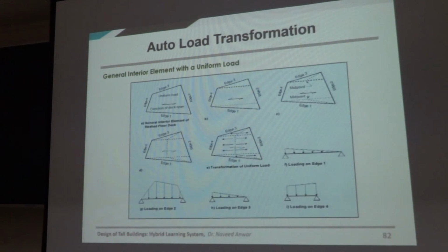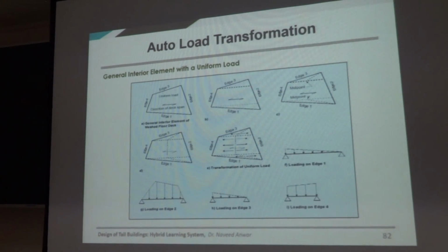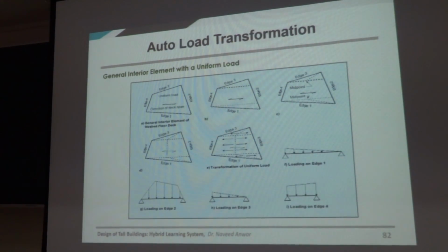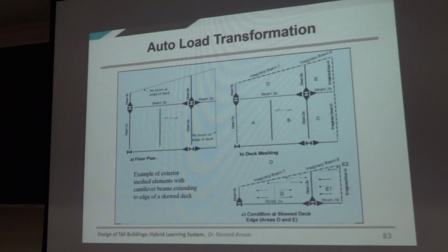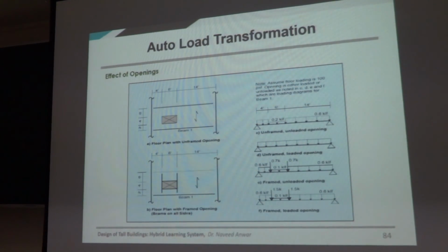And then many other cases are specified here. But I would never use geometry based load transfer for a complicated slab like this. Use shell elements, because this is not reliable. It's not correct. But yes, if you have to, you can. Even for openings, you can do some manual work. The reason all of this was given at some time was that this was essential to finish the project.